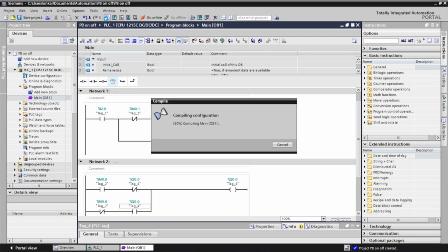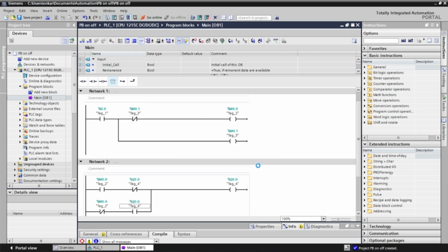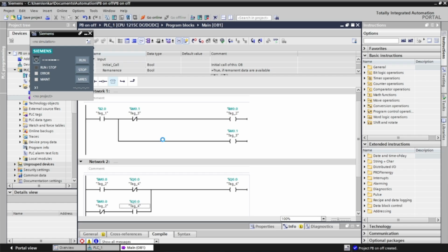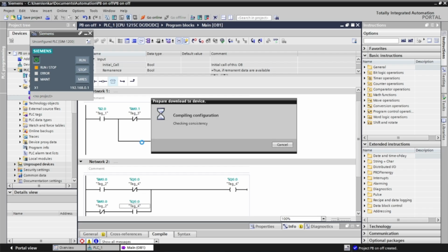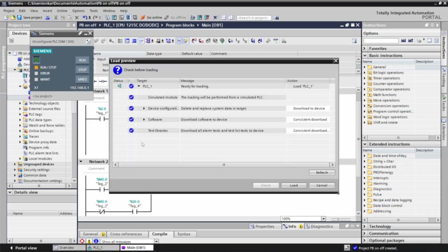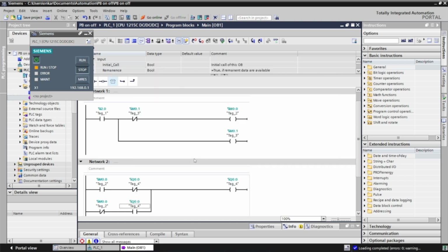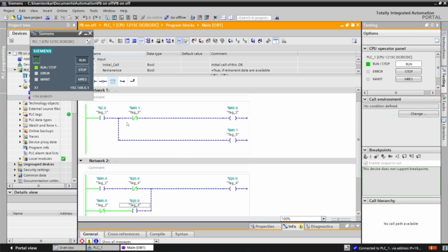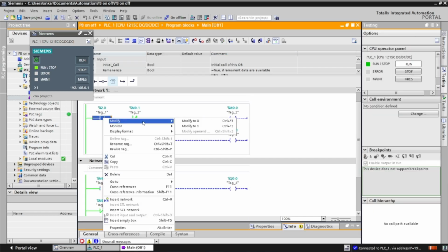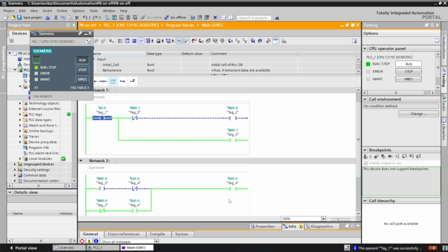Here's how it works. We're using a single push button, I0.2, to both start and stop the output Q0. When you press the button for the first time, the NO contact I0.2 turns on, setting M0, which latches itself on and also activates M0.1. But M0.1 is connected as a normally closed NC contact in the first network, so it breaks the latch immediately after one scan cycle. This gives us a momentary pulse, not a continuous on.